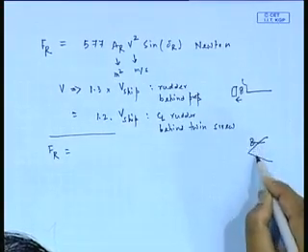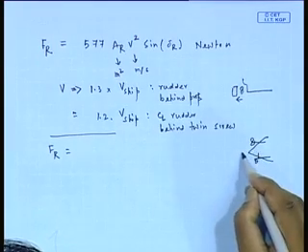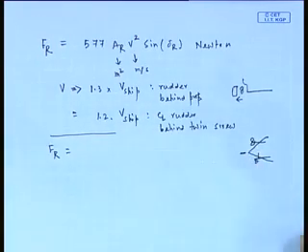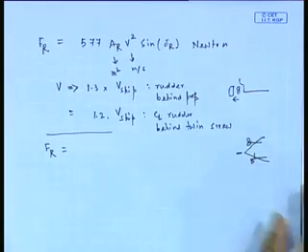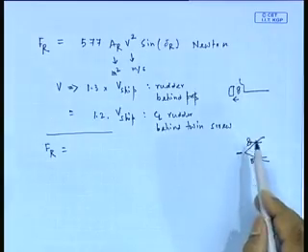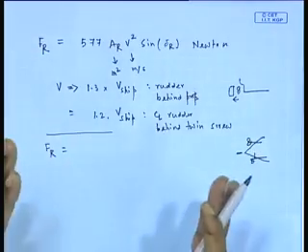There is a propeller here, there is a propeller here, but the rudder is here. This is what we call a centerline rudder behind a twin screw ship. See, your question is that even in twin screw I will have the rudder behind the propeller, but no, we are talking of that design where there is a centerline rudder behind twin screw propellers. So, it is not mandatory that you must have a rudder behind a propeller.